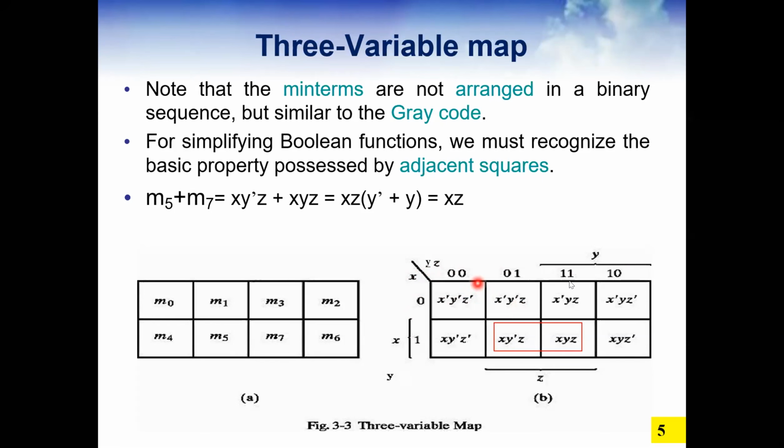You may think, why am I writing 1, 1 first? Why not in order 0, 1, 2, 3? Actually, this numbering is not in binary, this numbering is in Gray code. So 0, 0 will be the first column, 0, 1 will be the second column, 1, 0, that is 2 in decimal, will be the last one, and 1, 1 is 3 basically. But it is Gray code as I mentioned. So it will be 0 0, 0 1, 1 1, 1 0. This is the fixed rule.